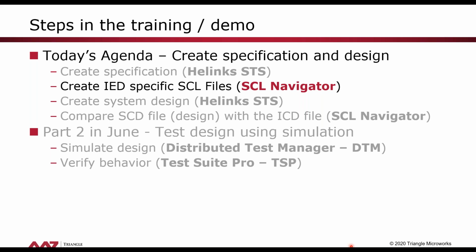Okay, and I do have another question for you, Christoph. Why is there a need for 2 separate logical nodes for breakers, for example, XCBR and CSWI? Okay, the XCBR, as mentioned, is representing the interface. So that's the pure image of the contacts that you would get in a conventional system from the breaker. The CSWI is the control function as such.